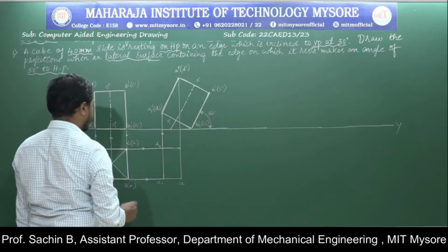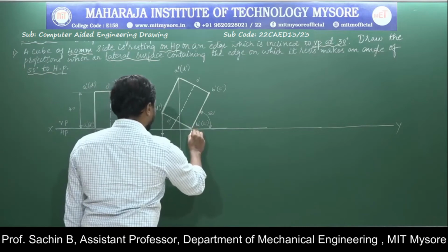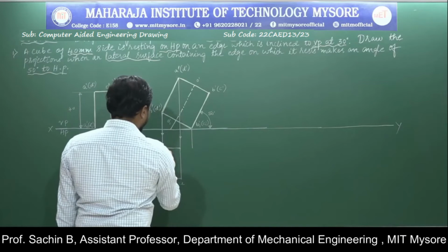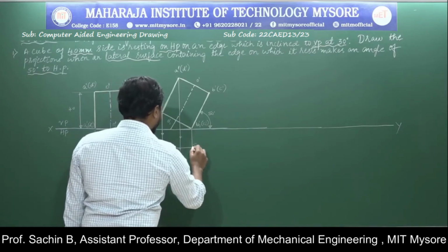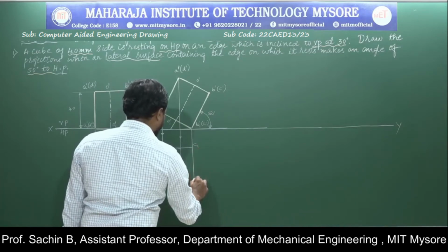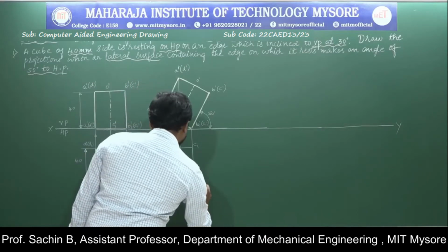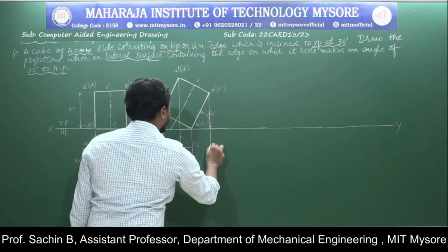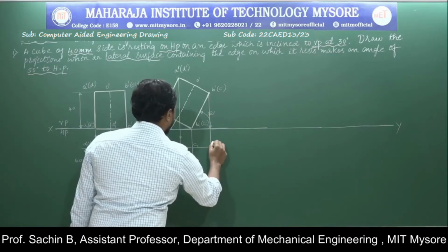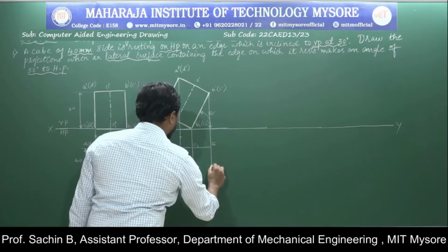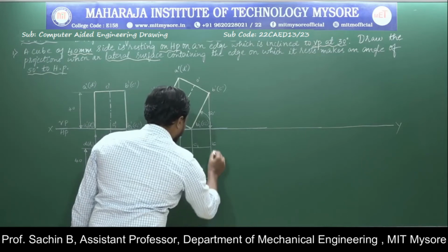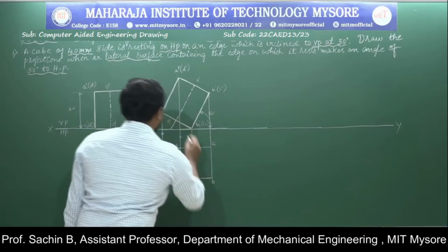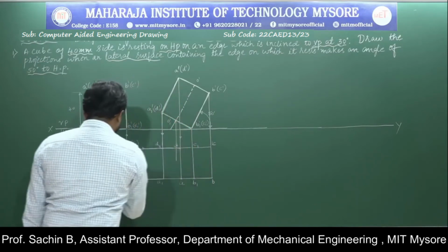This is A1. Next I will draw the projection line from B1 dash. B1 to C1, C1 is already here. I am extending this line. This is the C1 point. Next I will extend this line with a thin line. This is B. Again I will come to the B dash point. I will extend the projection line. This is the C point. I will extend the same projection line to the bottom position. This is the B point. Now I will draw the projection lines from the axis, again from the first position.